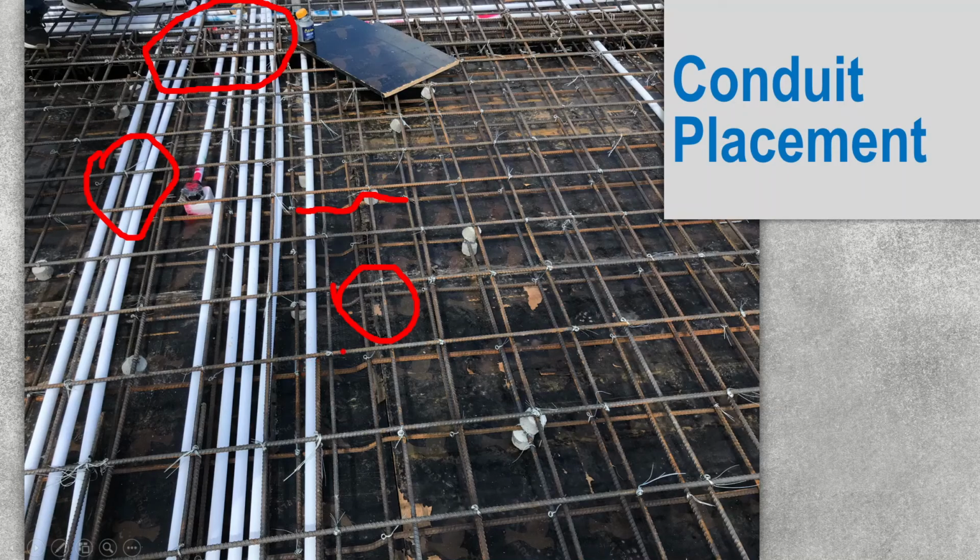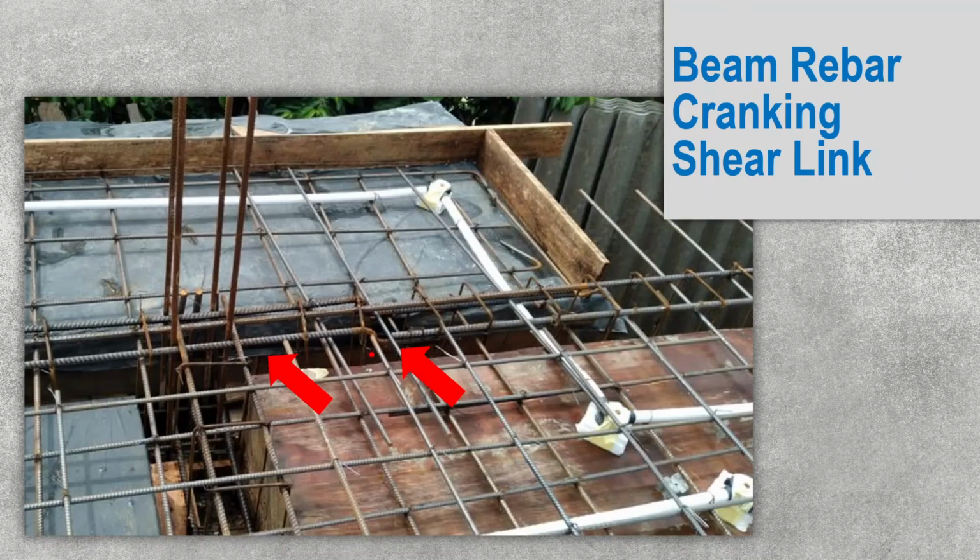This could lead to a structural failure, because when tension is applied, this bar will be straightened like this. Then there will be excessive deflection and cracking in the slab. This could even lead to a structural failure. As you can see here, what they have done is improper. You can see the bending of the reinforcement. At the slab, they have bent the reinforcement like this.